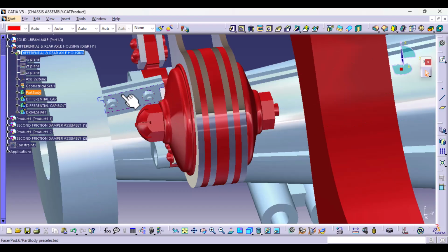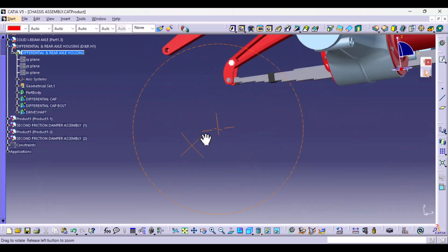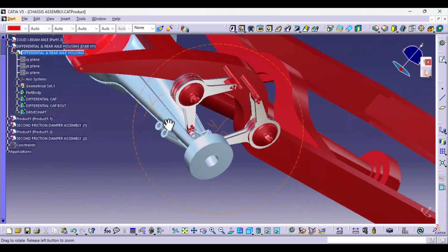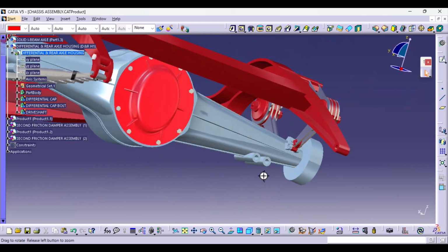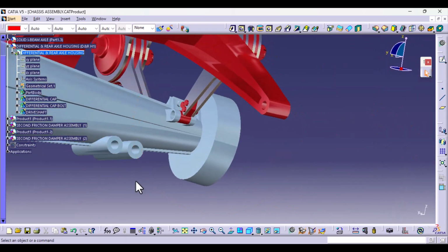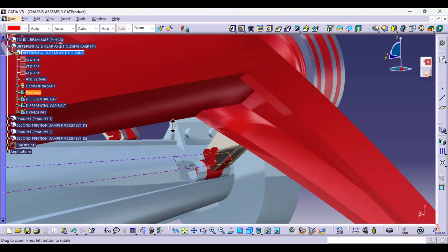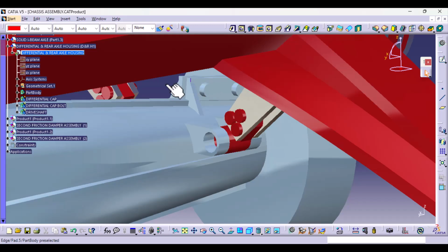I want it to move together with this initial component, and for it to do so, we need to make sure that the sketch of these subsequent parts have been constrained to the original element. That means if we had a rectangle here, we would have to maybe project a 3D element of this sketch and constrain them together. So that we don't have a lot of components here, so we can quickly go over them.